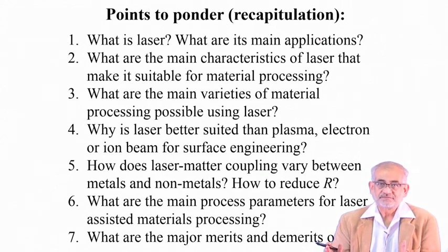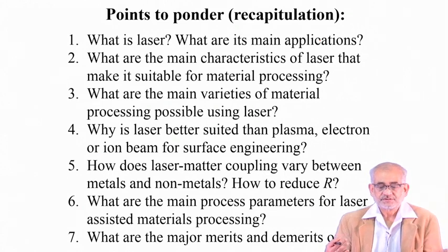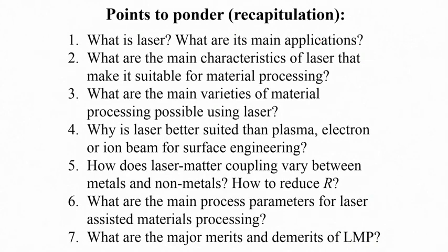The other side of the story is the material properties, which involve the melting point, the density of the material, the specific heat, and the thermal conductivity, which in turn will determine the heat transfer coefficient. All these will determine the thermal state, and the level and mechanism of thermal activation. What is good about laser is that the coupling efficiency is very fast. The way the incident laser photon gets converted into lattice heat takes less than a nanosecond.